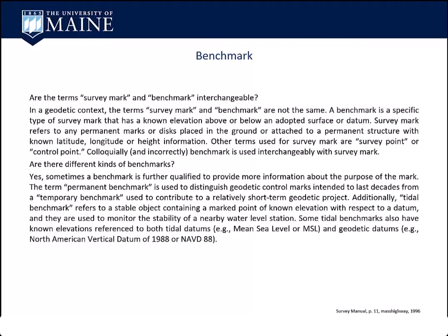It's going to give you ellipsoid height, and you're going to convert it to something. And the data collectors will do NAVD 88, straightforward, state plane coordinates, straightforward. It's not going to do tidal datums because they're apt to change over time. So be very careful if you're working on the water, and you need to do something.